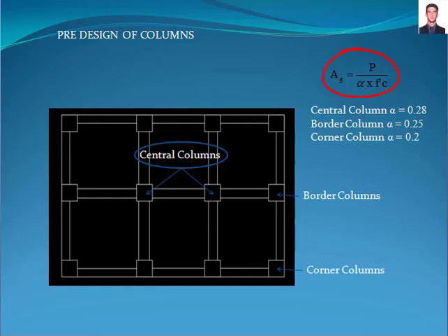And finally, f'c is the compressive strength of the concrete, which shall be 3,000 pounds per square inch as a minimum, as required in Table 19.2.1.1 of the American Concrete Institute 318 standard for seismic buildings.